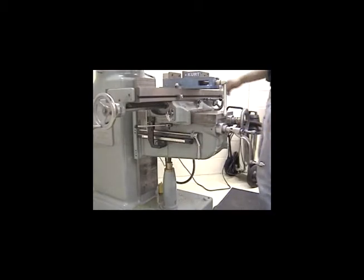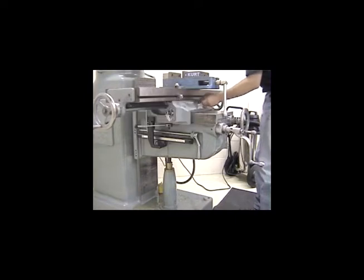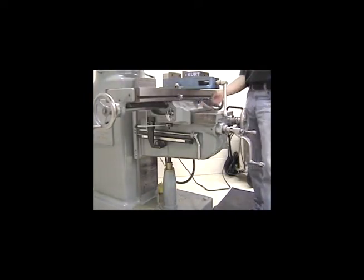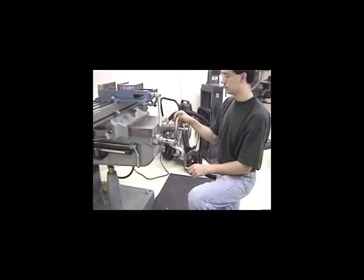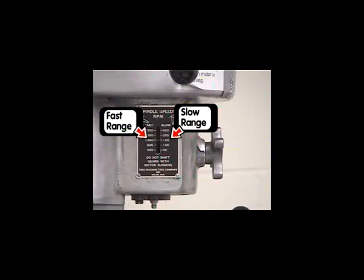To lock the table in place in the X direction, tighten the X-axis lock. Be certain that a direction is unlocked before engaging the auto feed in that direction. All three wheels or hand cranks have some play in them, so the crank can move a little without moving the table. The spinning speed of the mill has two ranges, fast and slow.